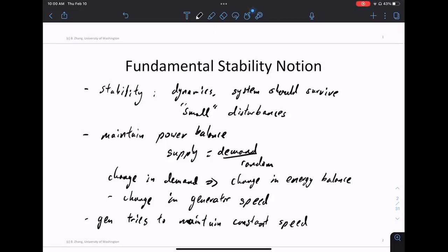Right now, how does a battery respond? Battery still thinks it's a synchronous generator. The battery is trying to mimic, like, "I'm a synchronous generator," through its interface, and that's how it responds. But a battery does not have to respond that way. A battery can do whatever control you want. It doesn't have to pretend to be a synchronous generator. You just don't know what it is. Suddenly, if you have all this freedom to design it, we don't know what to do.